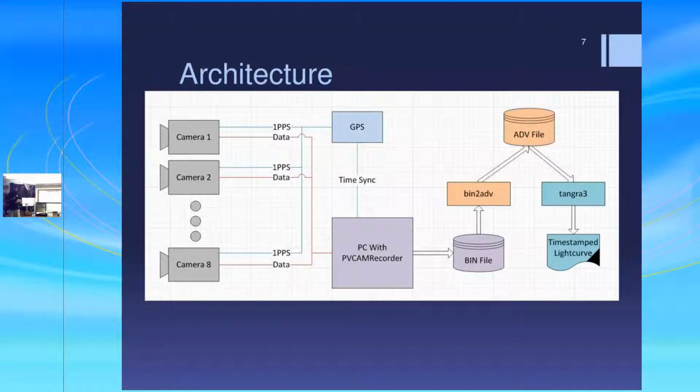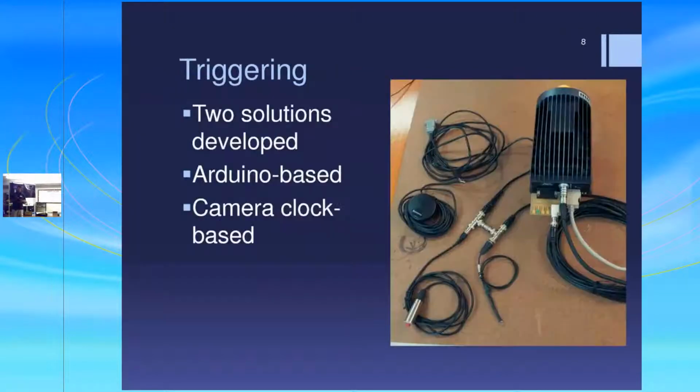One of the main issues with occultation timing is, of course, precise timing of the event. We decided to use the camera's external trigger input and then experimented with several ways of initiating the trigger. The simplest approach uses a camera trigger interface card we developed and a thumb switch to turn off the pulses. When the thumb switch is depressed, or was released, the very next pulse, whose rising edge, will trigger the camera and start the acquisition sequence.